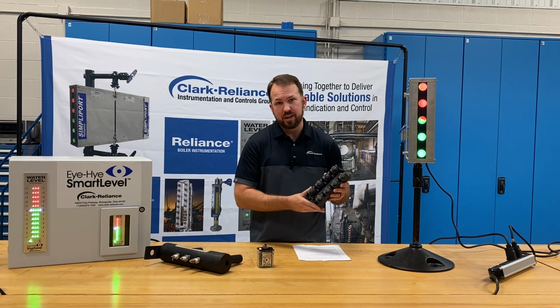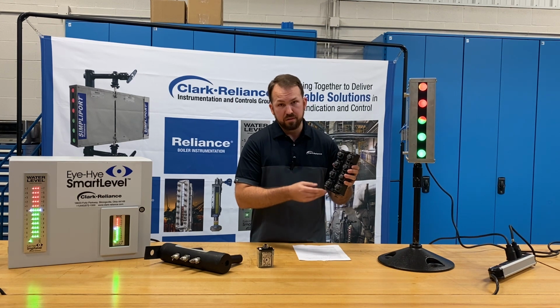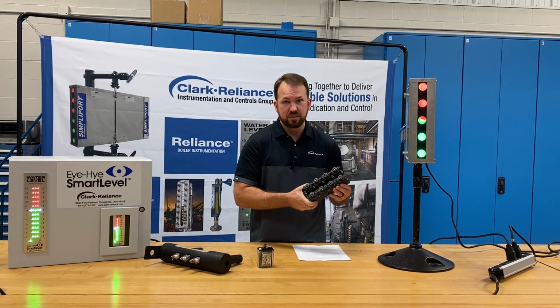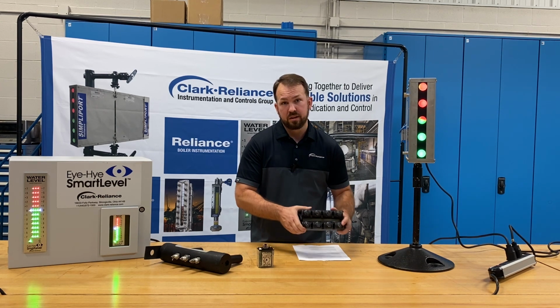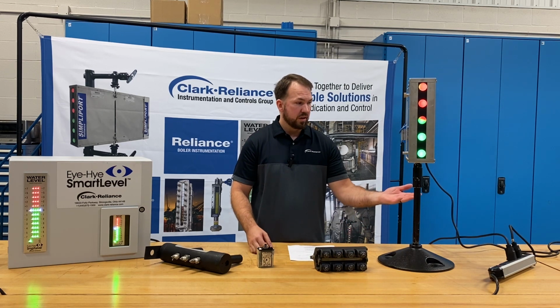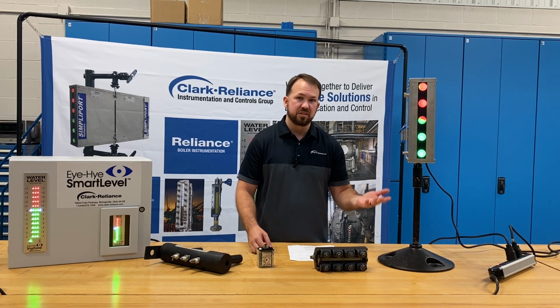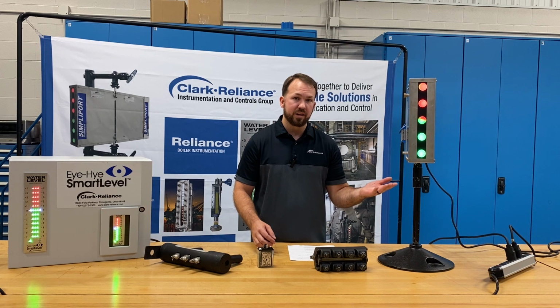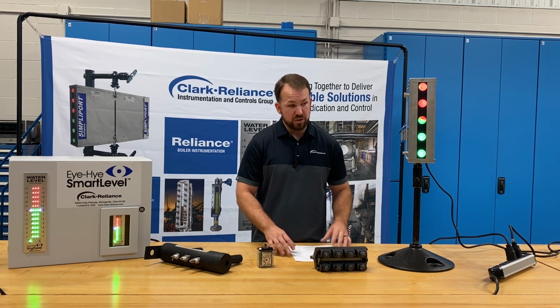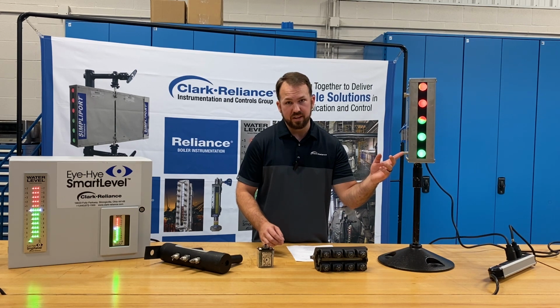A direct reading gauge is a gauge that you can physically see the water level in. An example of this would be our prismatic gauges like our RC and RS series, a flat glass or transparent gauge, as they're sometimes called, or here we have our simple port gauge. This is sometimes called a ported gauge or bicolor gauge, and it works with light refraction so that way you can see the level inside the gauge, but you still are physically seeing the water inside that gauge.